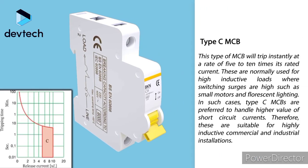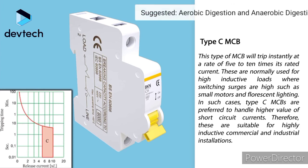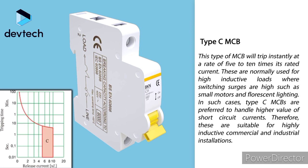Type C of miniature circuit breaker. This type will trip instantly at 5 to 10 times its rated current. These are normally used for high inductive loads, where switching surges are high, such as small motors and fluorescent lighting. In such cases, Type C is preferred.